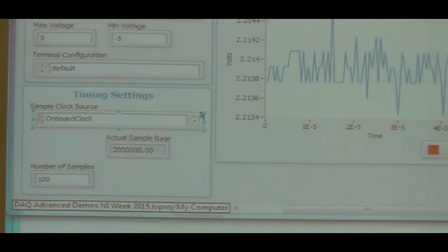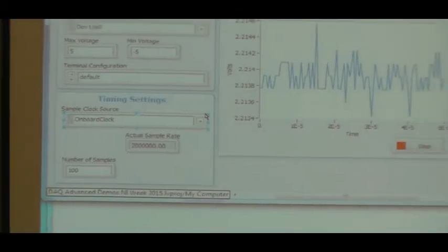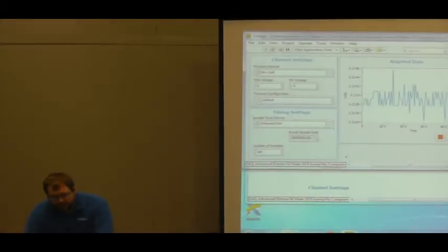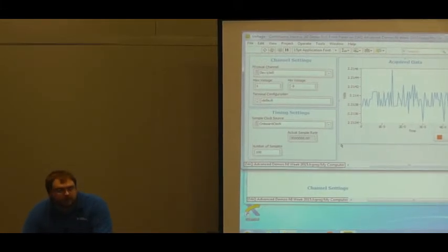And so what's the special case? Because my customer application is a combination of 9211s, 9213s, and 34s. So the special case for those slow sample modules is that those will return repeated data at a faster rate when you put them in a task with a faster module. There's a nice white paper that if you search for cDAQ slow sample modules, it'll talk about how it chooses what rate it's going to run at.